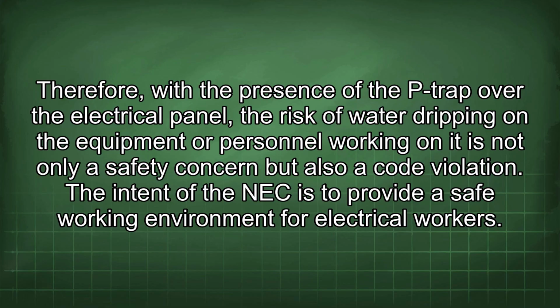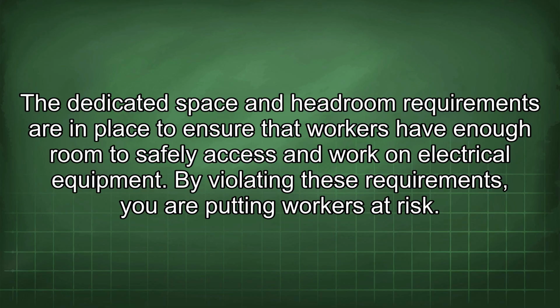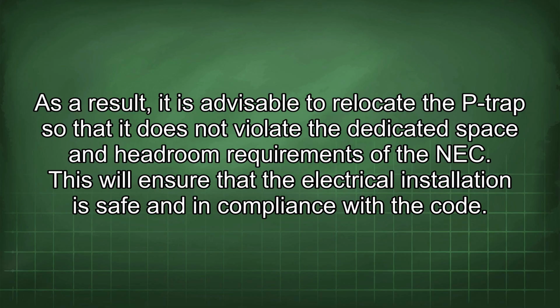The intent of the NEC is to provide a safe working environment for electrical workers. The dedicated space and headroom requirements are in place to ensure that workers have enough room to safely access and work on electrical equipment. By violating these requirements, you are putting workers at risk. As a result, it is advisable to relocate the P-trap so that it does not violate the dedicated space and headroom requirements of the NEC. This will ensure that the electrical installation is safe and in compliance with the code.